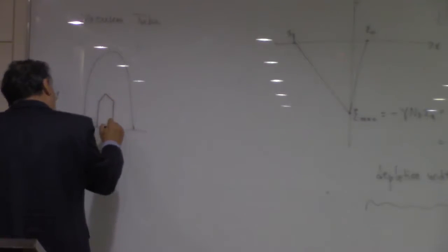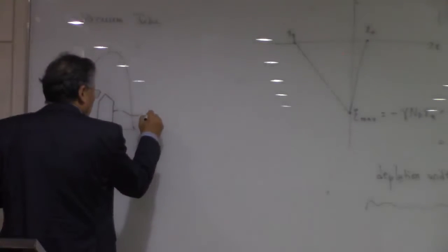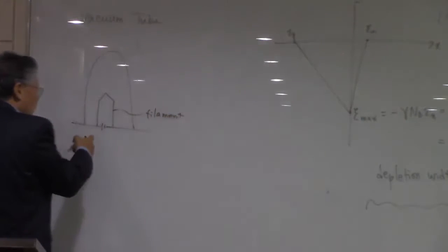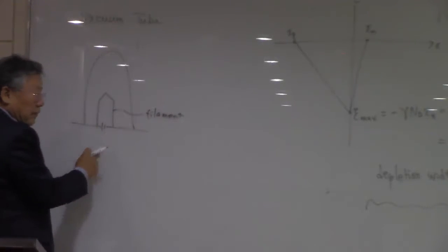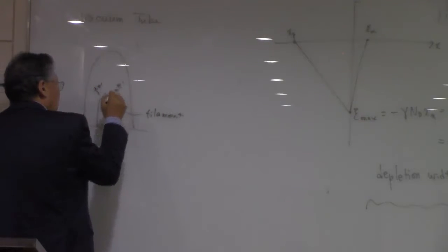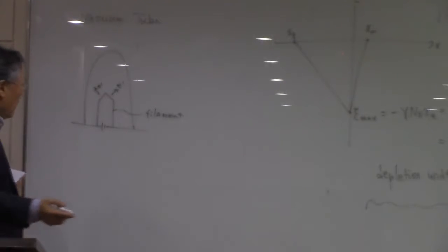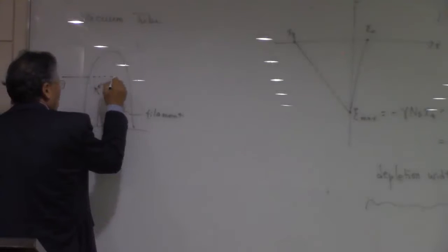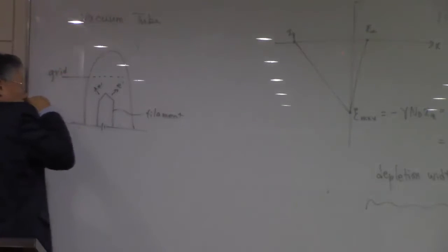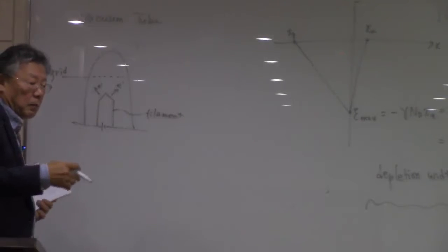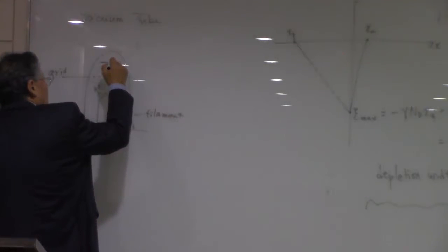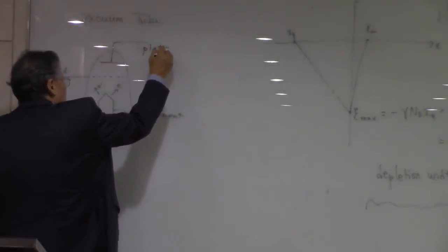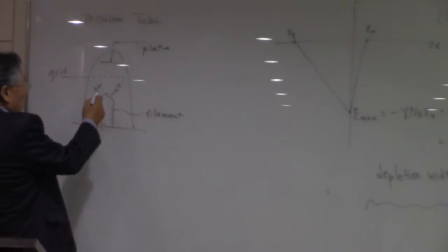you catch the filament, and then if you keep this filament inside the vacuum tube and then apply some voltages, then electrons are going to be emitted, and we call this field emission, right? And these electrons are going to be modulated by the grid. We call this the grid. And in this grid, all you do is just put plus and minus small voltages here. And then we set inside the vacuum tube the plate. We call this the plate. Okay, and it receives the electrons which have passed through this grid.